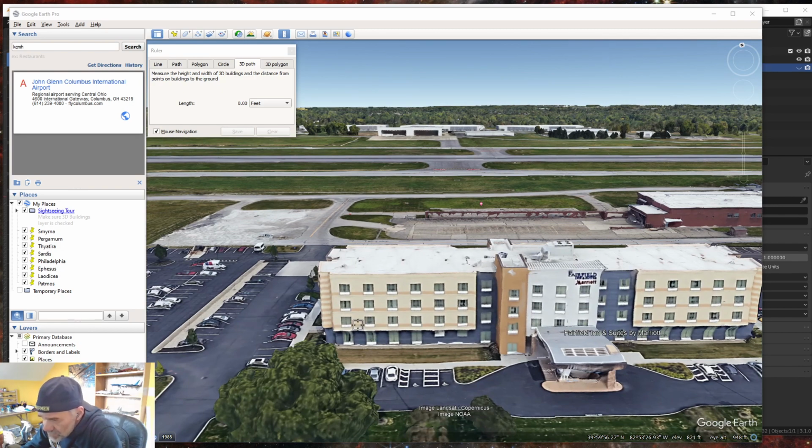All right, now we'll make these stripes, okay, but just want the figuring out where the tops and the bottoms of the windows are. Now, remember, the standard size of a floor in a commercial building is 10 feet, and then they usually have a suspended ceiling 2 feet below that. It's for duct work and things like that. So floor to ceiling is 8 feet.